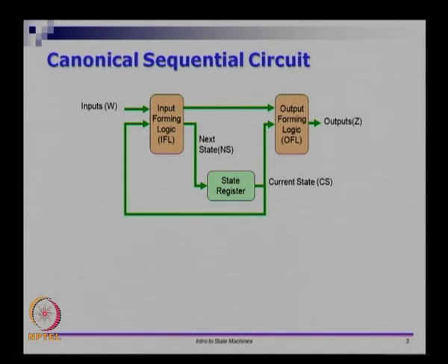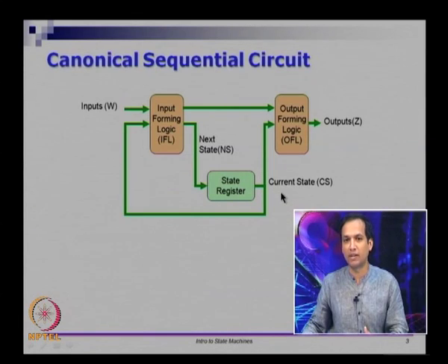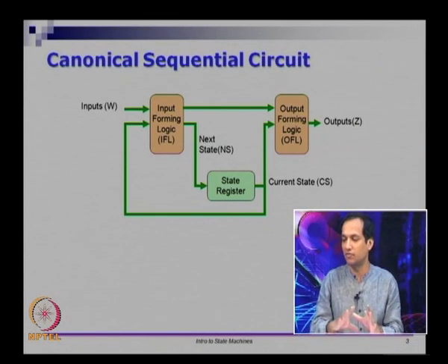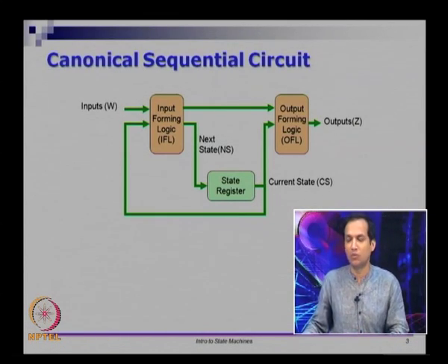It is a register, which means it takes in a value and you can also tap it out in parallel. You can give inputs in parallel to all the flip flops, and you can also tap out the values in parallel from all the flip flops. You can go back and look at the parallel in parallel out register, just in case you want to refresh what the state register is. It is just a basic register, a collection of flip flops, each one can take one input and give one output. The collection of these flip flops can all be accessed in one cycle.